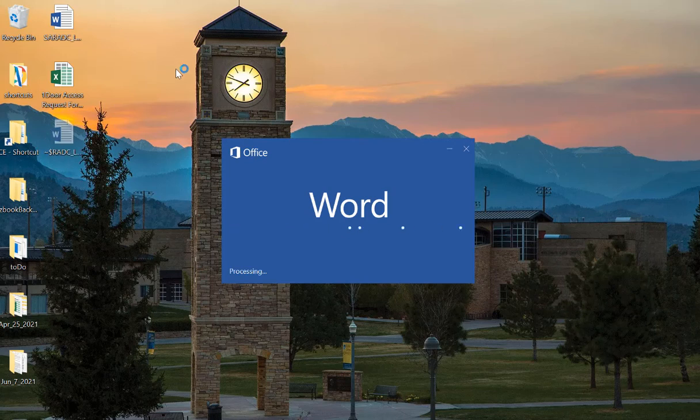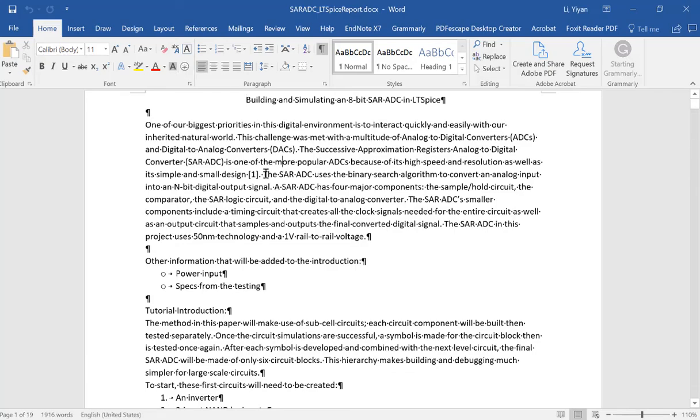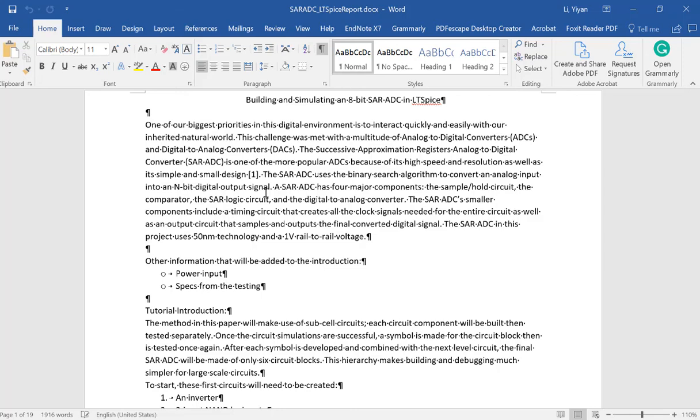And here's a sample of the course project. It was done by another student who worked with me in the past summer. And we actually designed every single component in the SAR ADC, and it worked. So it's not an ideal ADC anymore, like the ones you are going to simulate in the lab next week. It's something you can convert into an IC chip. And that's what we are doing for the senior SUM team this semester and next semester to really tape it out. Tape, T-A-P-E, out. That's a term used in the IC industry.